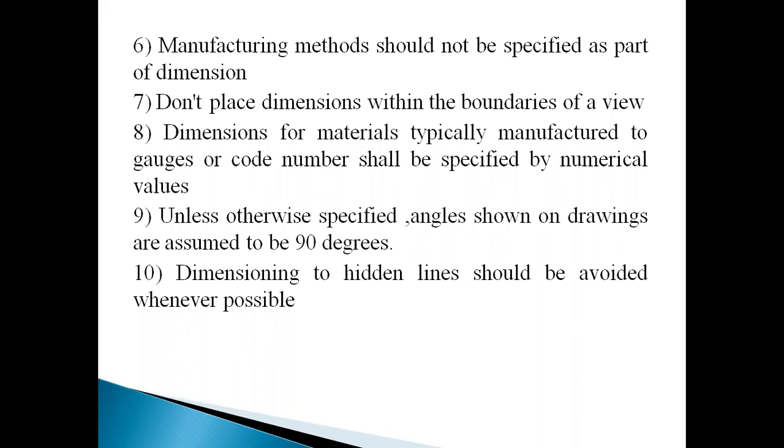That is, each dimension shall have a tolerance except for those dimensions specifically identified as reference, maximum, minimum, or stock. Dimensioning and tolerancing shall be complete so there is full understanding of the characteristics of each feature. Nothing should be assumed, and neither scaling nor assumption of a distance or size is permitted. Each necessary dimension of an end product shall be shown.